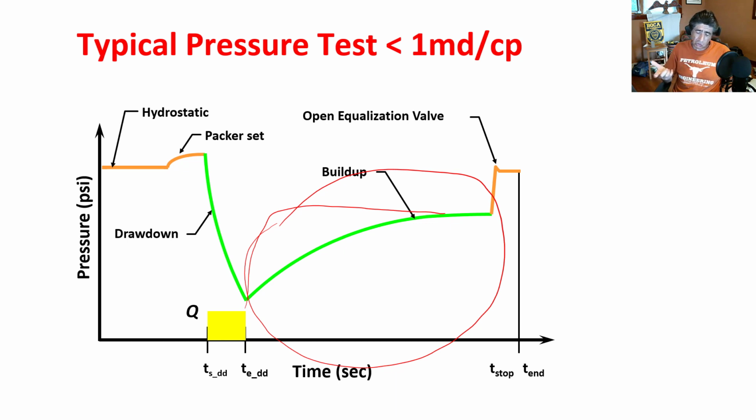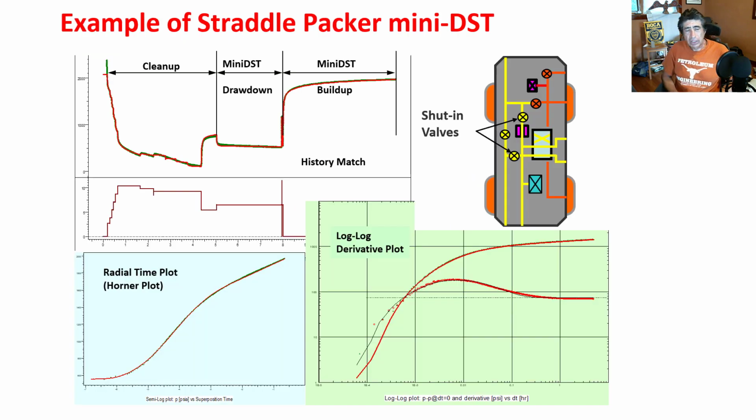transient pressure analysis to understand the different flow regimes and also to understand the average fluid transfer properties of the rock. And here's an example of samples done where you are doing multiple cycles. This can be done on multiple cycles of build up and drawdown to basically clean the flow line and also to make sure that the probe is making proper contact with the formation.